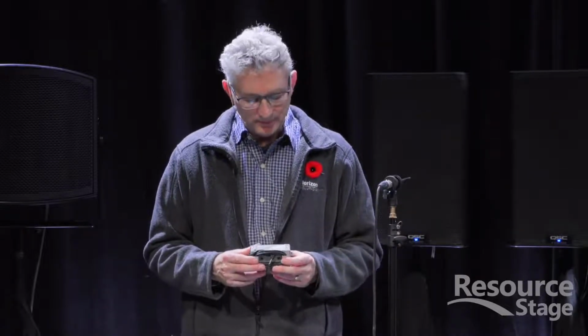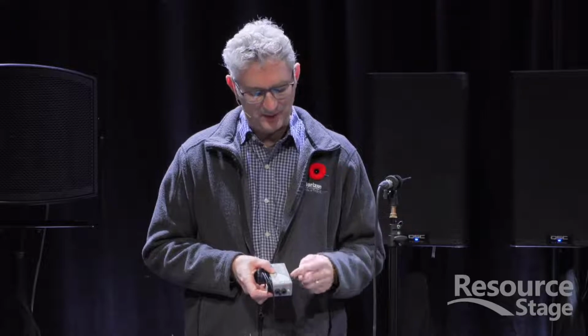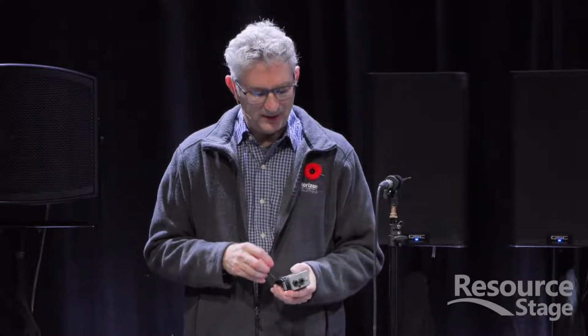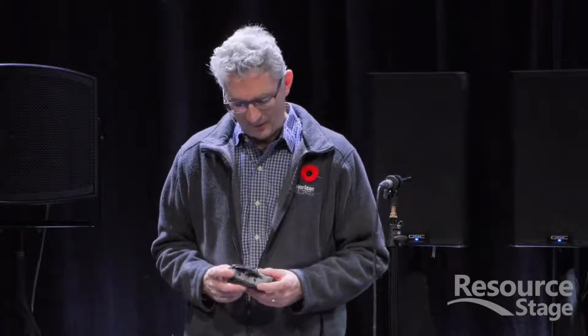So if you need to do some isolation going to a mixing console, the reason why they did that, there's a couple of reasons. One is this cable is coming in as a stereo connection, left and right. So the XLR does the mono sum to it, and you might not want to sum both of those. That's where the two outputs here, actually labeled left and right, come in. So you can continue that on, plug those into your 1/4 inch inputs of your mixer if you needed to, and do that. This is a very handy tool when you're connecting computers or direct boxes into your sound system. Again, we often run into hums and buzzes and a variety of different problems that come up, and this is a great little problem solver for doing that.